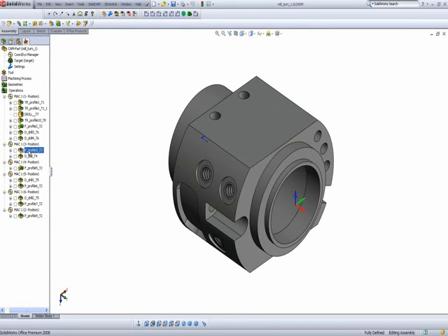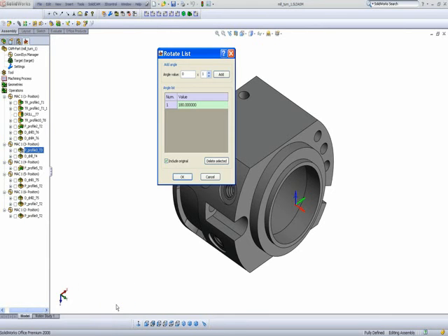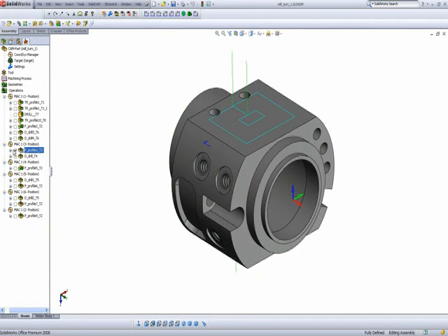In other words, I'm working on a 4-axis indexial operation here. What I've actually done here is I've gone into what we call transform, and we have here 4 axes. And as you can see, what I've told it over here is to do my original operation and then add another operation turned at 180 degrees, thereby causing it to work on both sides, this side and on the other side.